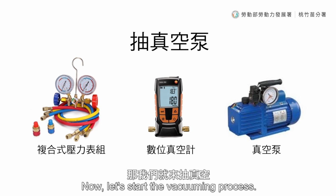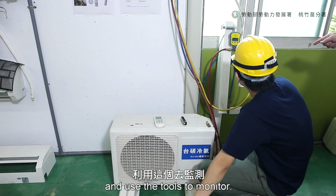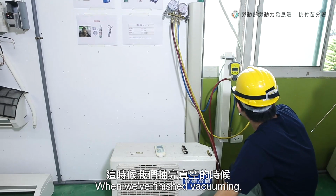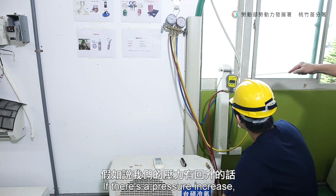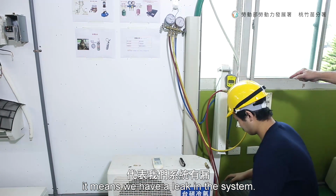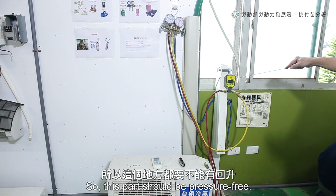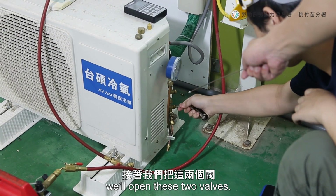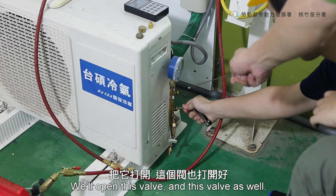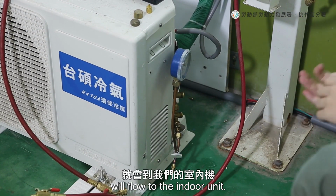Now let's start the vacuuming process. We place the pipe here and use the tool to monitor. When we've finished vacuuming, we need to check the pressure. If there is a pressure increase, it means we have a leak in the system. There shouldn't be any pressure increase in this process, so this part should be pressure-free. After checking if everything's fine, we'll open these two valves. We'll open this valve and this valve as well. At this point, the refrigerant will flow to the indoor unit.